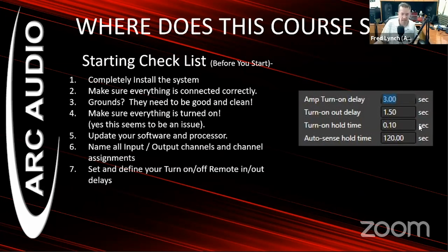The turn on out delay is something that controls the output trigger to additional amplifiers. You never want to hook up a DSP and all your amplifiers to the remote turn on output of your source, because you are 99 times out of 100 going to get turn on pop. So if you're running more than one amplifier, like if you're running a secondary amplifier off of a PS850, or if you're running an additional amplifier off of an ARC series amplifier with an IPS 8.8, always run it out of the turn on output. And this secondary control here, which is turn on out delay, is where you will actually make that adjustment to delay the turn on sequence of that additional amplifier.